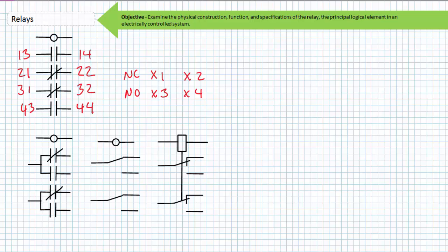Ice cube relays with single pole double throw switches use a similar numbering scheme. The first digit is assigned the number of that particular switch. This is the first switch associated with this relay, so each terminal's first digit would be 1. The common terminal's second digit is 1. The second digit is indicative of a switch's deactivated state, similar to previously. A normally closed switch is assigned a 2 as a second digit. A normally open switch is assigned a 4 as a second digit.